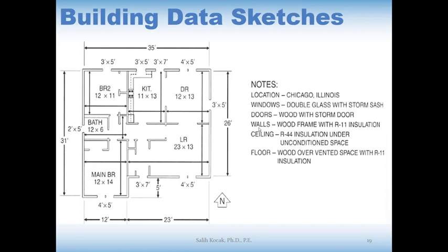Okay, so in the worst case scenario, as I said, if you don't have anything, we can just create one. It's really not hard. We're just gonna get a few people, 2 people is enough, 3 is better, to measure the sizes of the building and make some basic sketches, show the dimensions on that one so that we can calculate the volume. Based on that, we can do all our other calculations.